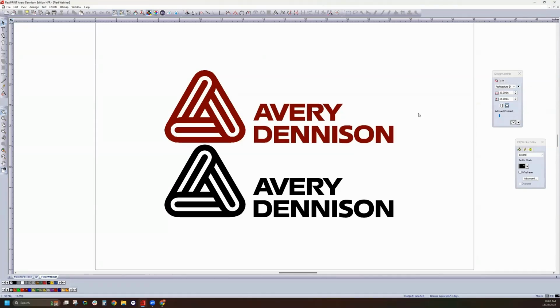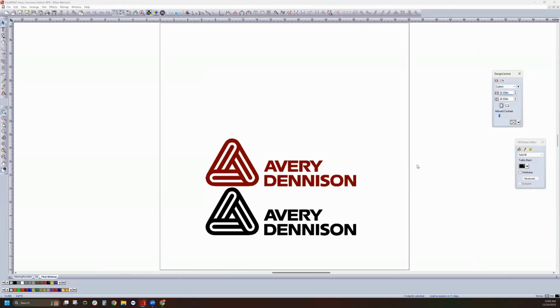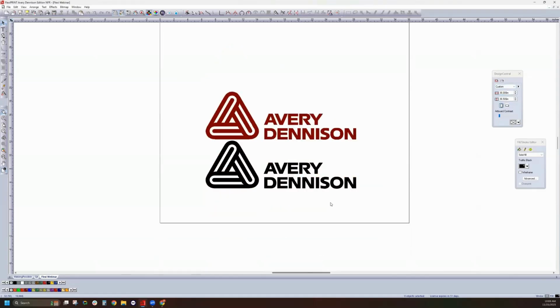Another tip that a lot of people like to use as well is they like to set this width up to be the width of the sheeting they're going to be printing on, or the material they're going to be cutting their signs out of. So I have this one set up for, it's 36. This is the default, but we can change the size of that as well, and make it anything we want, really. So it's just a visual guide. This border will not print. That's a pretty common question that we get. It's just there for your convenience.